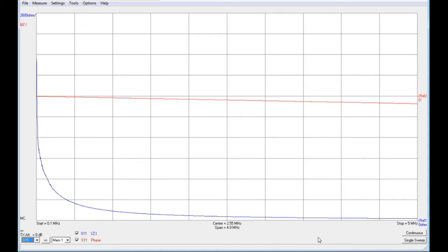So first of all, if we have a look at the range that we want to take it over, well, I want to start by taking a wider scan. I've designed this cylindrical Tesla coil so it works in the 160 meter band unloaded. So the middle of that band is 1.8 to 2 megahertz. I've nominally arranged it to free resonate around about 1.9, 1.95.